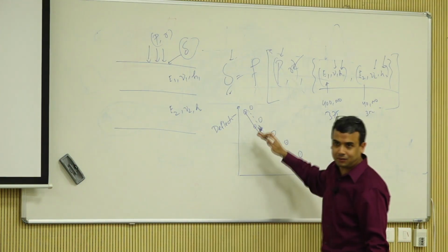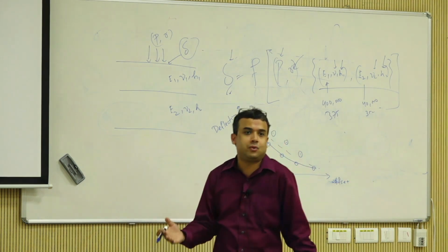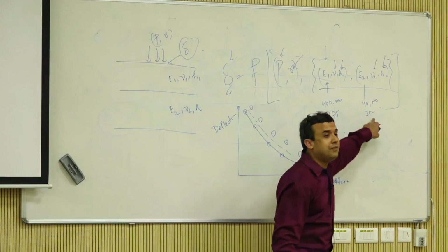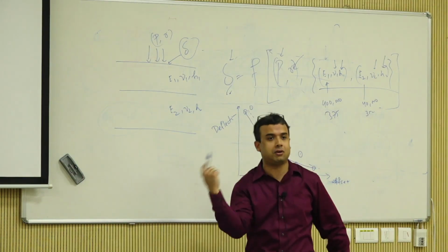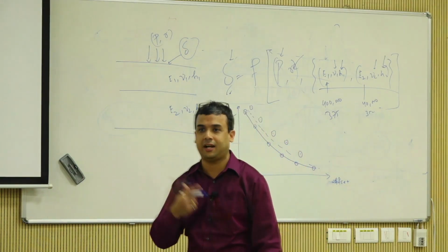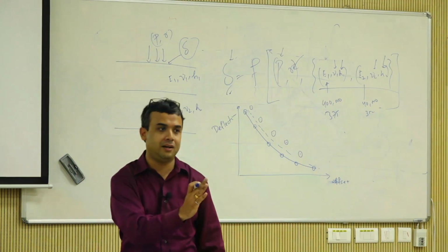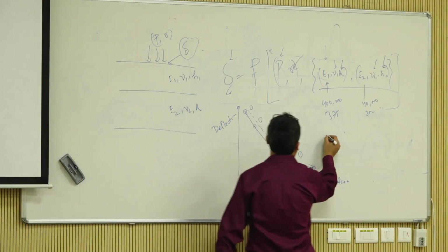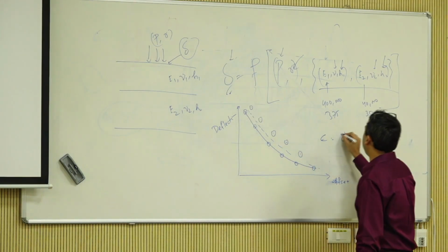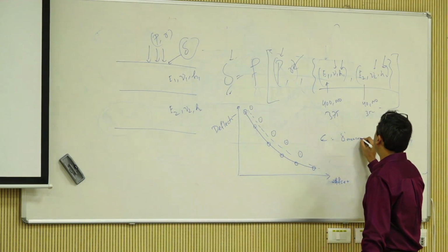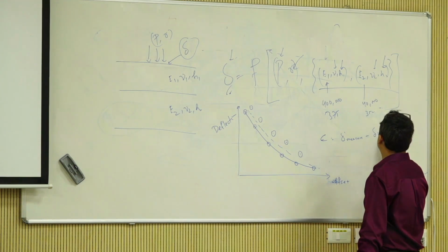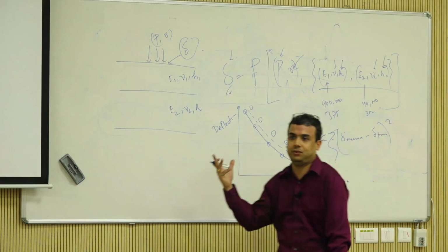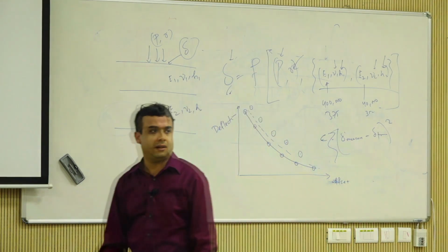Then you have another one, and ultimately you converge. It's not that straightforward, because if you change the two values together, you're going to be chasing your tail your entire life. You have to have a strategic approach, and there are convergence algorithms where error is equal to delta measured minus delta predicted, squared, summed over all the sensors, and you just do that, right?